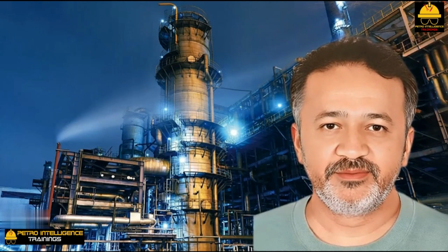This explains why venting a small amount of non-condensibles often has the dramatic effect of increasing condensation rates, especially when condensing pure components such as steam. I also believe that this explains a problem that I've seen several times in steam turbine exhaust vacuum surface condensers. That is, an apparent large loss in the steam heat transfer coefficient, due to a relatively small air leak into the vacuum surface condenser's shell.